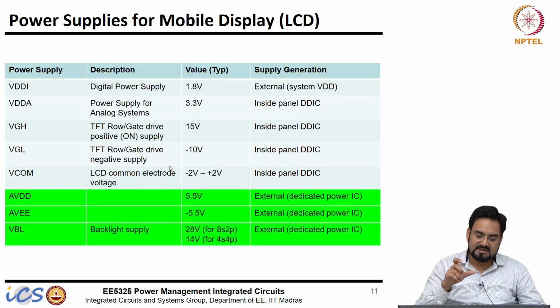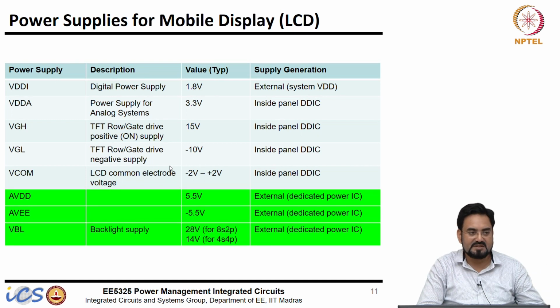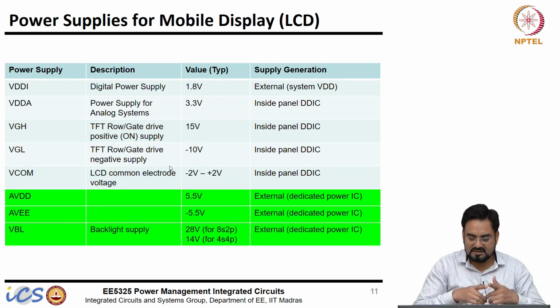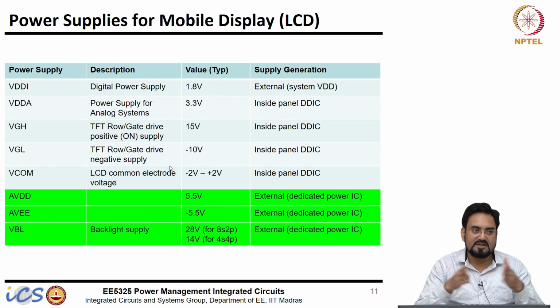And that's how, when we talk about how you control the brightness of an LED, the same concept is applied here. You turn on and off at such a high rate that our eyes will see a constant light, but by changing the duty cycle, you can change the level of brightness.